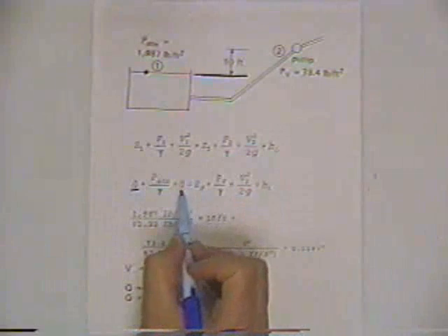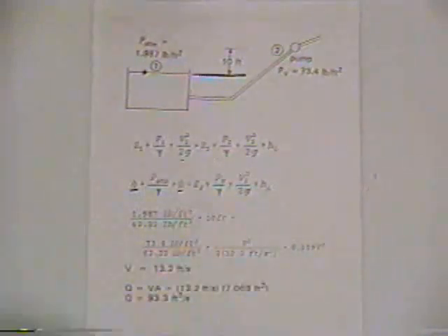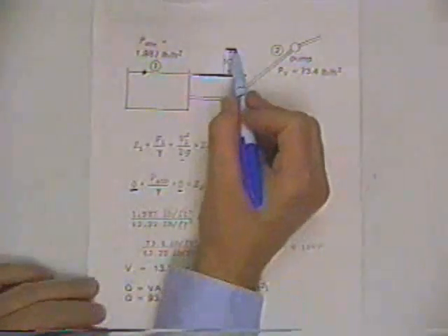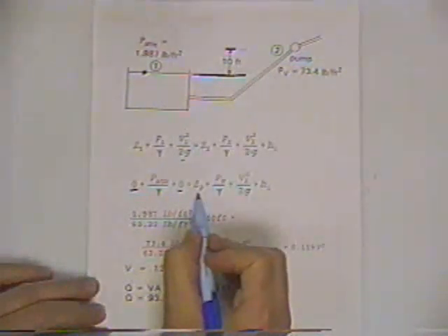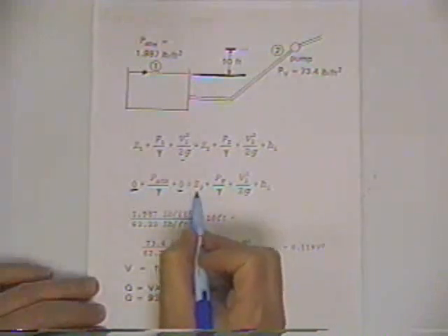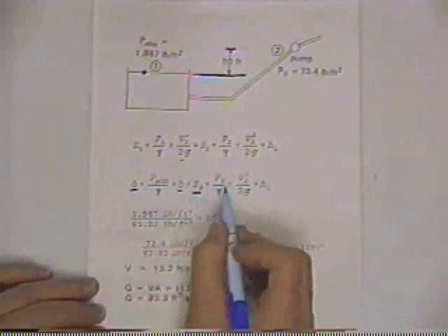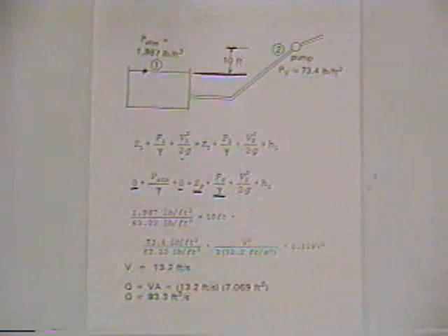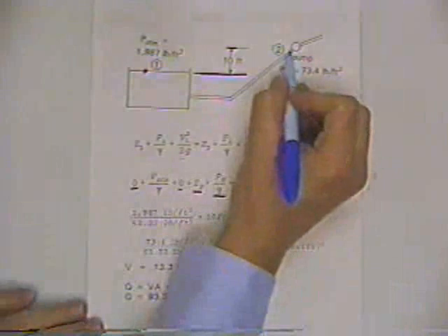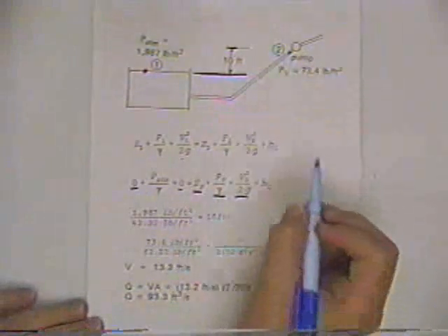We'll let the velocity be 0 again, and so the velocity head is 0. Now, just generically, we could call the height at which the pump is vertically located above the sump Z sub P, and we're going to set this pressure equal to the vapor pressure. The reason we're doing that is because we're recognizing the physical situation that we don't want vaporization to occur. So that's part of the statement of the problem. And then there will be a very definite velocity of flow here, and that's the velocity head.